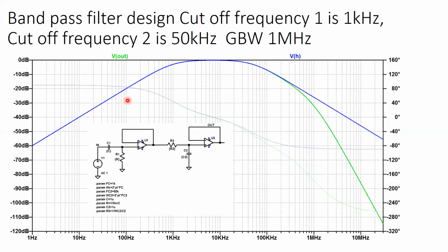So if I were writing a lab report, here's my theoretical Bode plot. This is what I measured. What's the difference? I would make a circle here and say it's the gain bandwidth limiting what's going on. You can come up with an equation for it, right? Just using AV over S. All right.